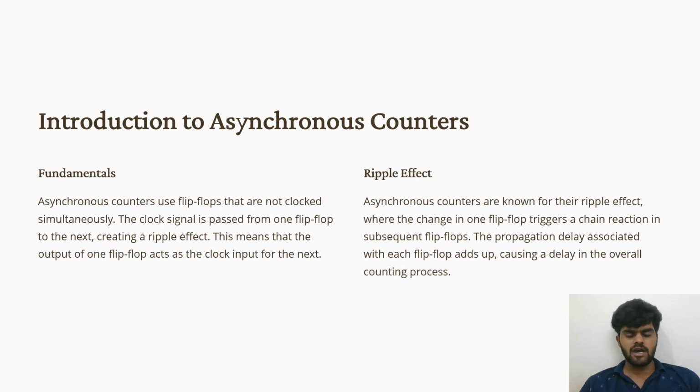Ripple effect. Asynchronous counters are known for their ripple effect, where the change in one flip-flop triggers a chain reaction in subsequent flip-flops. The propagation delay associated with each flip-flop adds up, causing a delay in the overall counting process.